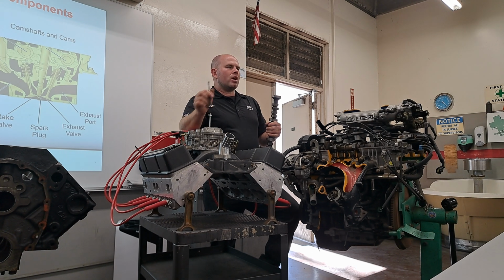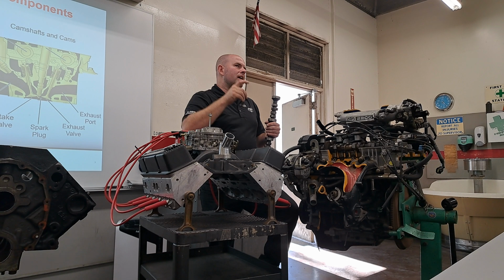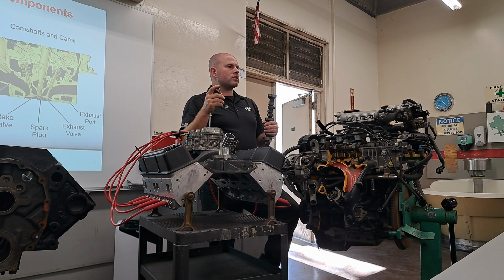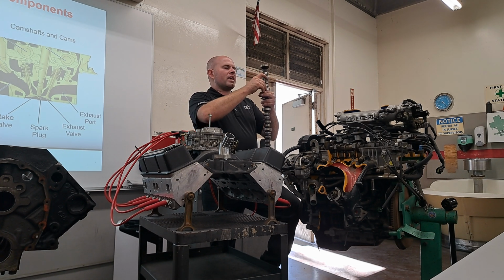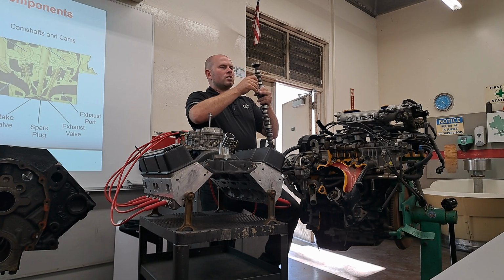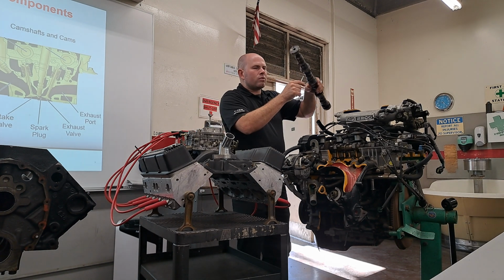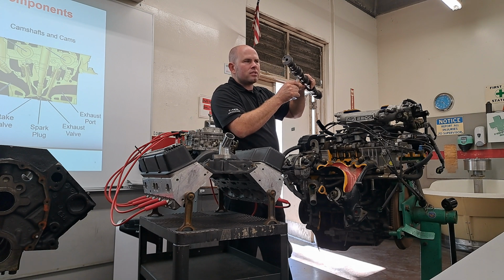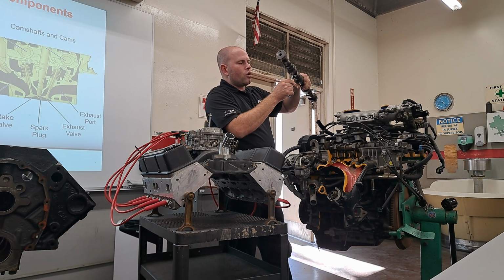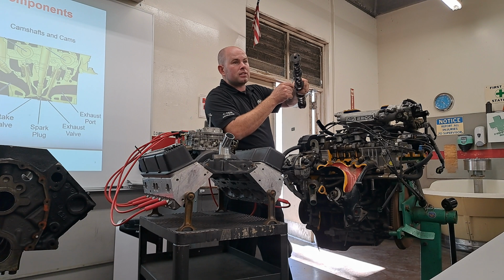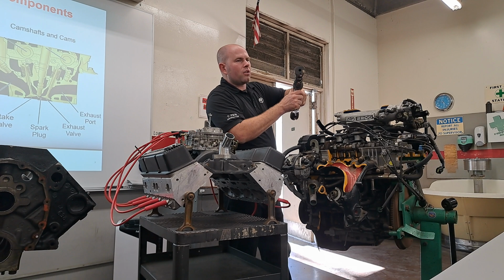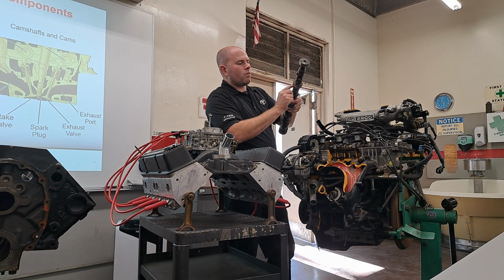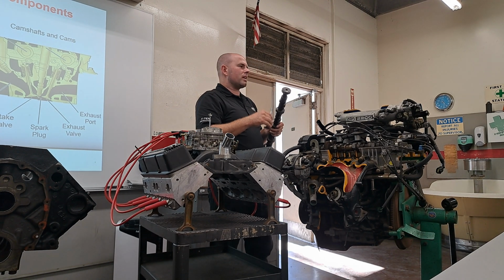Your valve adjustment should typically be maybe 7 to 11 thousandths, depending. Intake might be a 7 and the exhaust might be 11 thousandths. 7 thousandths of an inch clearance. So it's technically not really up against the cam. It's got about 7 thousandths of an inch. Then once the cam rolls and starts to ramp, it hits, and then they are touching, right? It opens all the way, and then it comes back around and starts to close. Once it gets on what we call the base circle, there should be about 7 thousandths clearance right there.